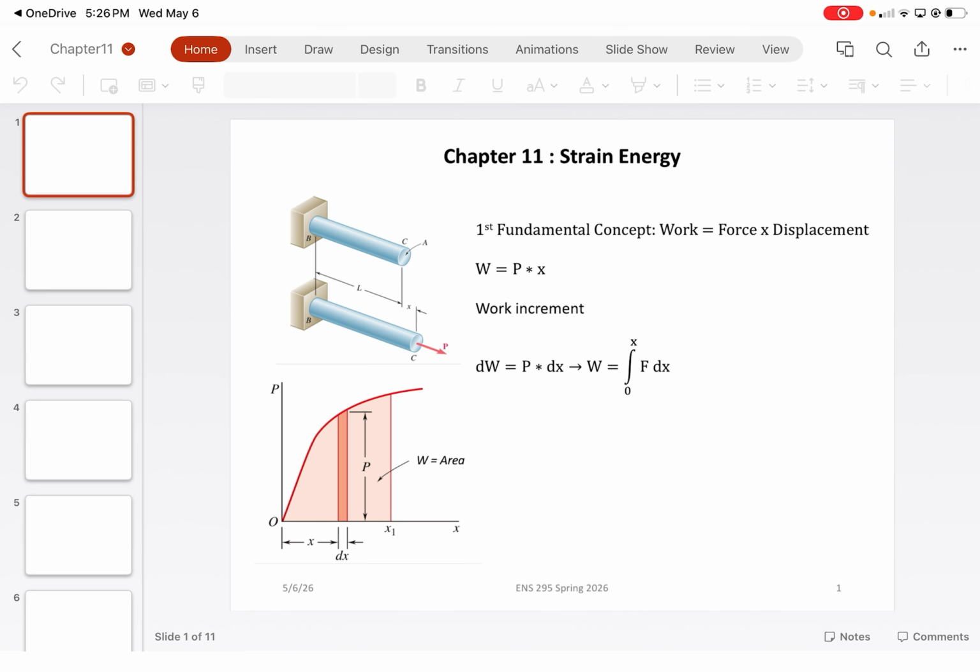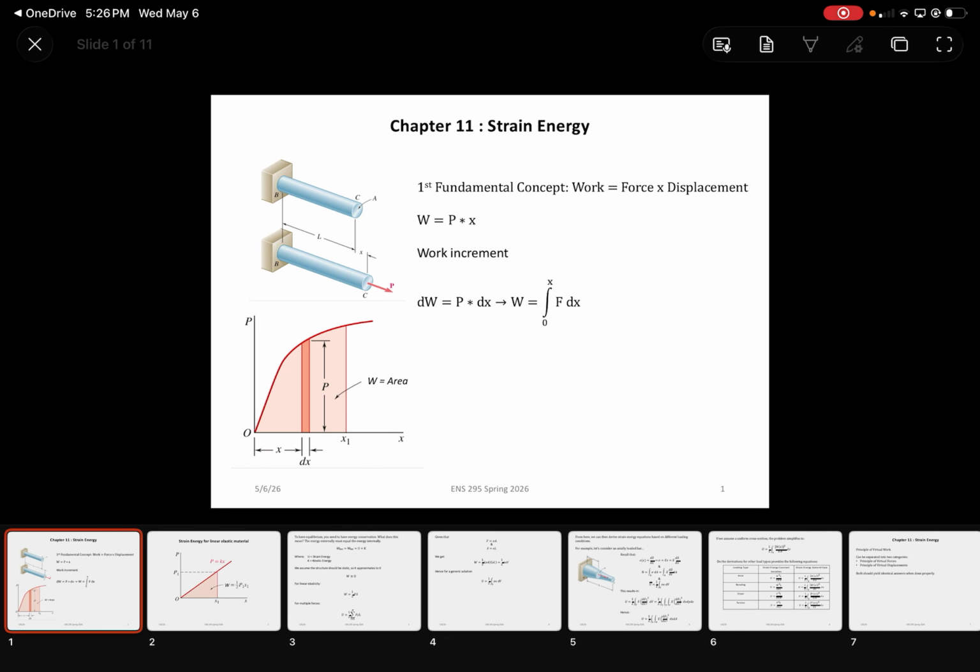All right. So, strain energy. Strain energy is one of my, if not my favorite topic in this entire class. Basically, everything that we have been dealing with so far has included Hooke's law, right? Force is equal to some spring constant, or as we derived it, just stiffness, whether it be axially loaded stiffnesses, bending stiffnesses, and so on and so forth, where the stiffnesses are dependent on material and geometric properties.